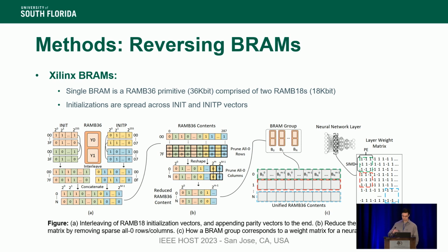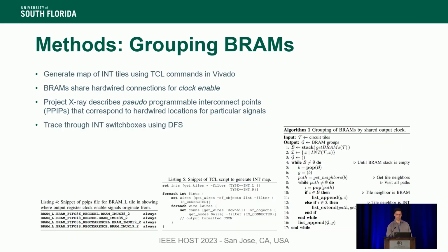And once we've performed this for all of the blockrams and we have grouped them all together, if you read the data from the groups row by row, like 0, 1, 2, 3, the data that's actually stored in them starts at like the top left-hand corner of the weight matrix for a neural network layer, and then traverses down and all the way until it gets to the bottom right-hand corner. And the amount of data that's stored in there and how much is in each row is determined by the folding parameters from FINN.